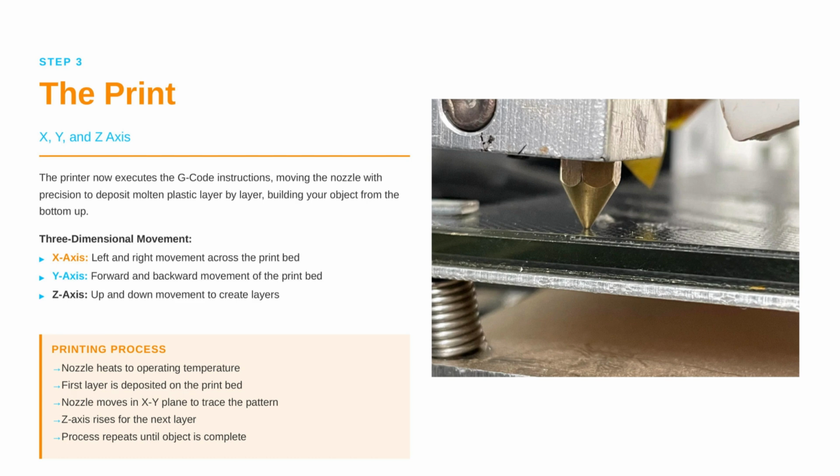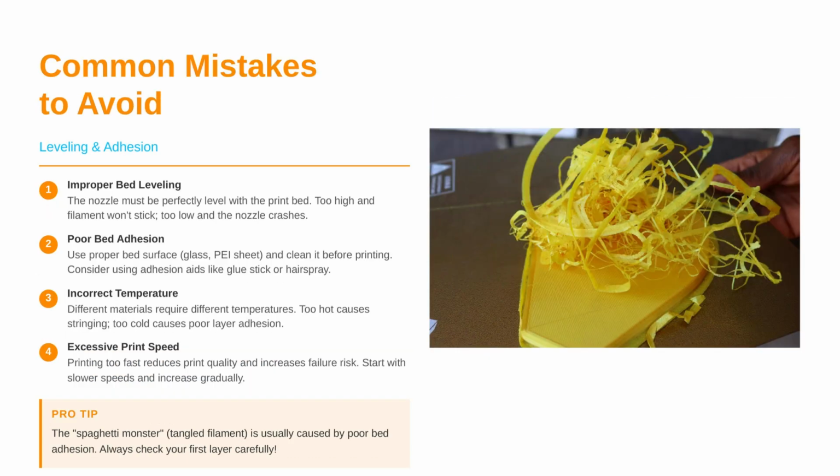Thermal management is critical during this phase. The material must be maintained at a temperature that allows for flow and adhesion but cools rapidly enough to support the subsequent layer without deformation. Successful printing relies on the seamless integration of these kinematic and thermal controls. We must also consider the common pitfalls that can disrupt this delicate process.